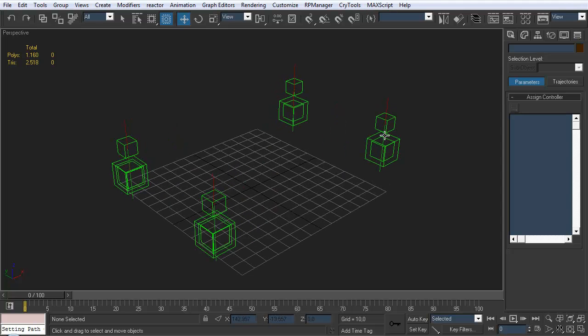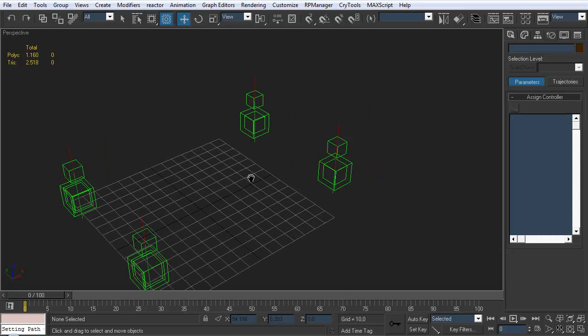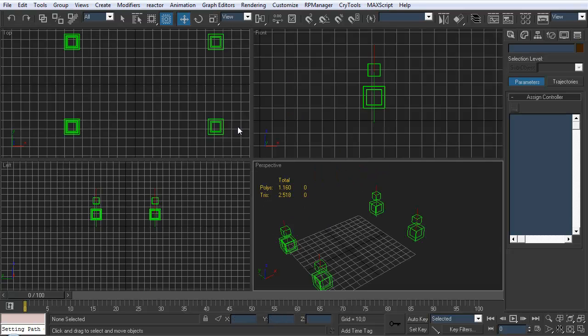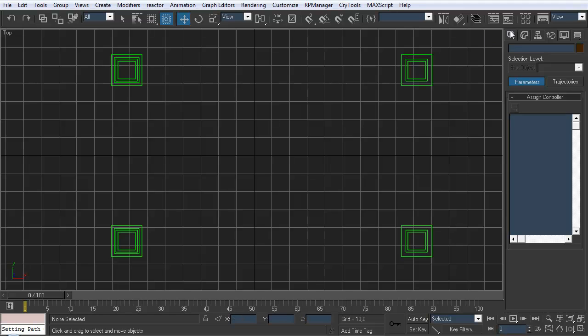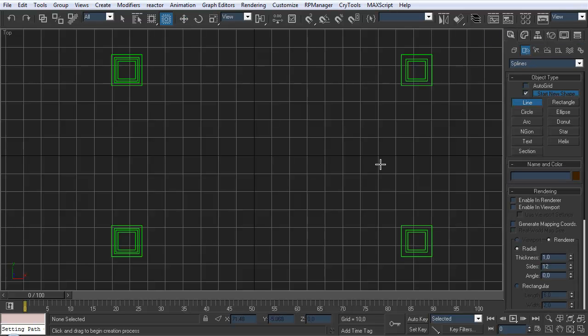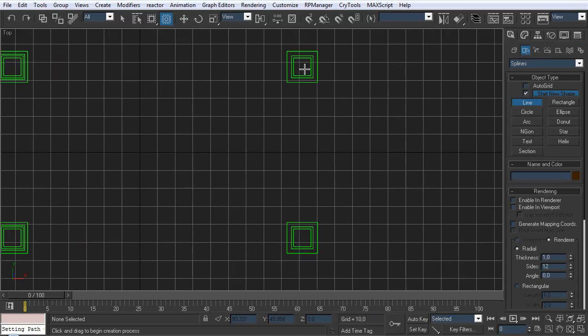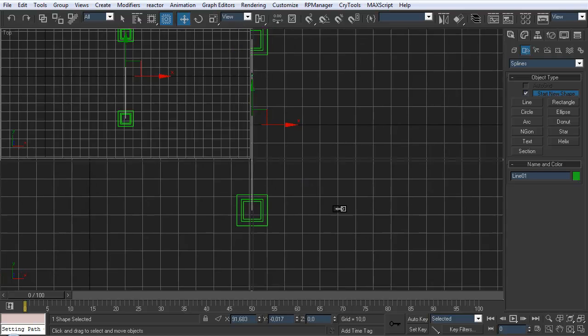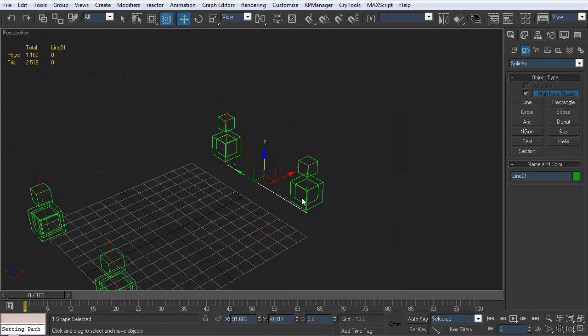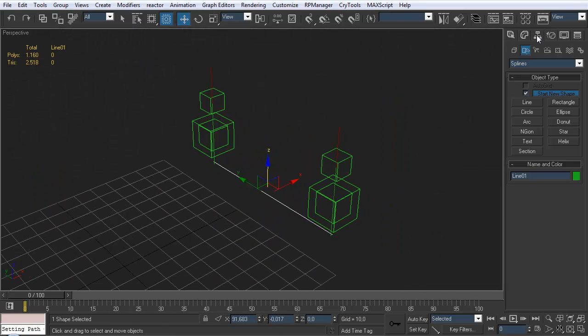What we want to do is create a sort of axle linkage between the two that will simulate the roll of the specific axles. To do that, we are going to have to create a new component. Go to Objects, Line. You want to create it between the two wheels. Just doing this in top view, estimating things as I go. Back to perspective.